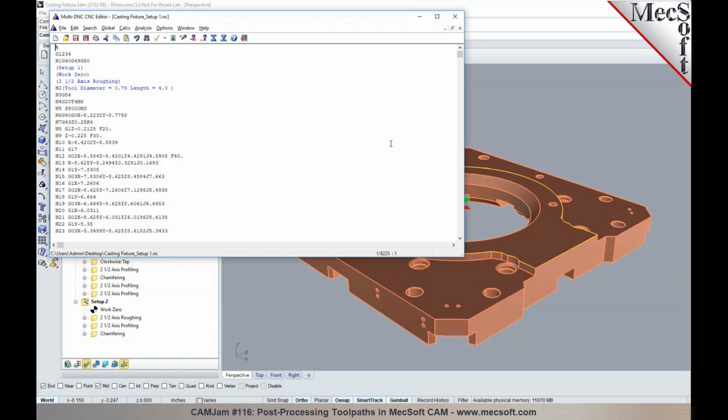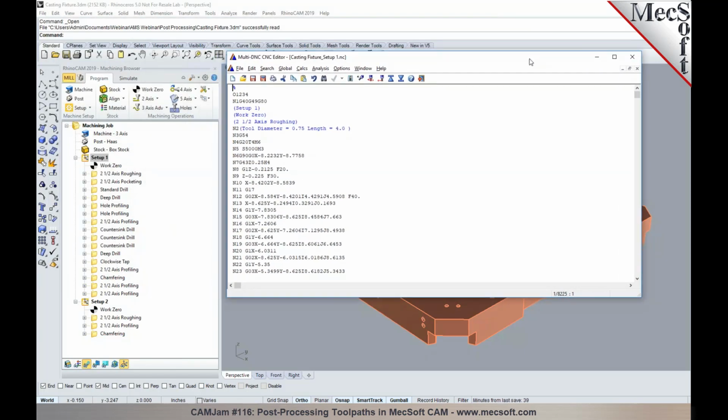And this can be done in all our products. One important note here, whatever program that you set up in that dialog needs to be able to take the name of the G-code file as a command line argument. If that executable does not accept the name of the G-code file as a command line argument, then all you will do is launch that program and it's not going to read that file.